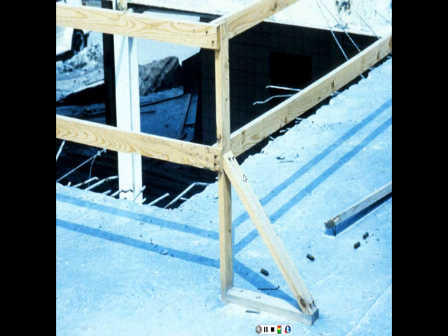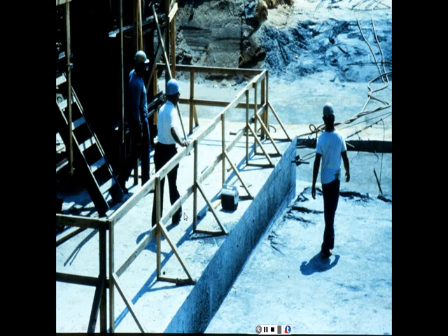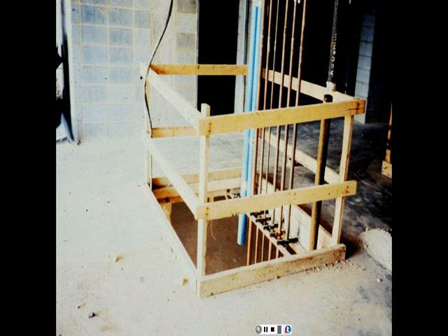This one is well reinforced, so this is a good practice. And since we have installed it away from the opening, then in this case we don't need the toe board, because nothing's gonna fall directly on the people standing under this opening. So this is fine. This is fine as well.